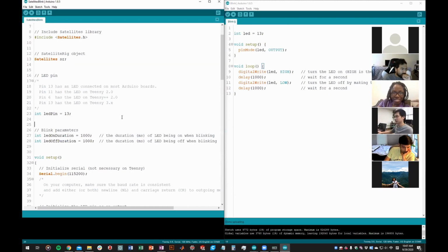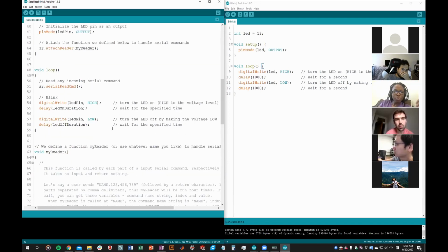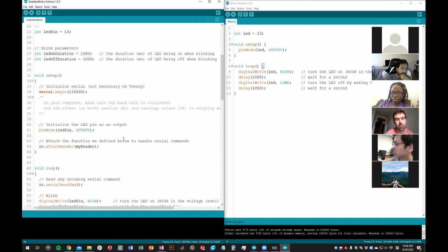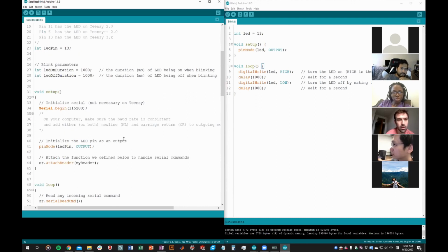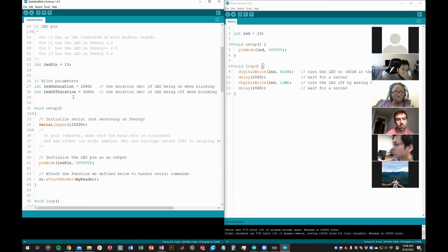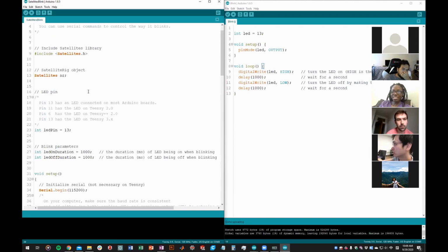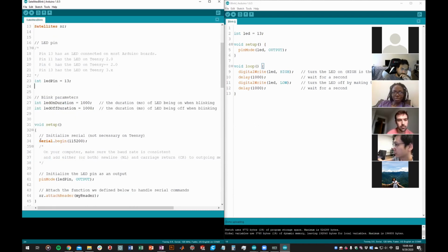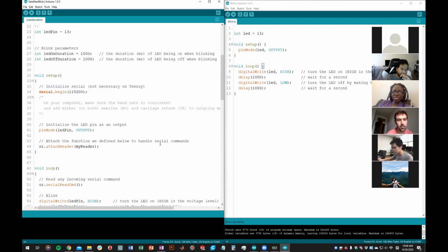Oh, okay, I see. Maybe this is kind of an irrelevant question, but what is the added benefit of running line 34, 41, and 44 in the context of a function as opposed to just running it outside of a function? So you cannot run functions outside of setup or loop. You can only declare variables outside. Okay. Yeah, not executing functions outside. Okay, cool. Yeah. Thanks.